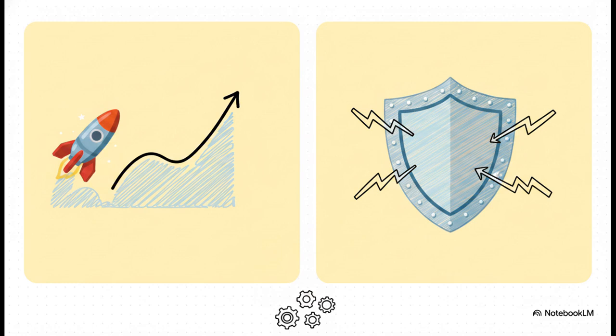So before the math really ramps up, let's take a quick mental breather and distill what we've learned so far. The philosophical difference is honestly pretty clear. If your priority is the absolute fastest response with controlled overshoot, you're going to reach for the CHR method. On the flip side, if your priority is aggressively rejecting those random disturbances and minimizing that integral error, you lean on the Cohen-Coon method. It's kind of like having two completely different tools for two very different industrial realities.